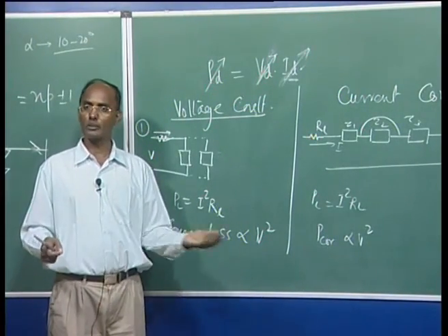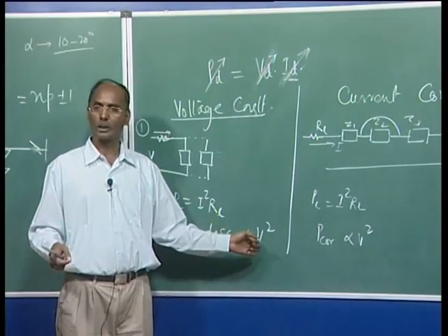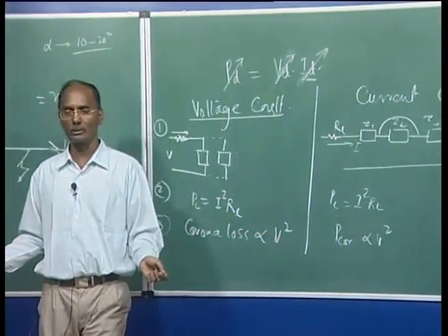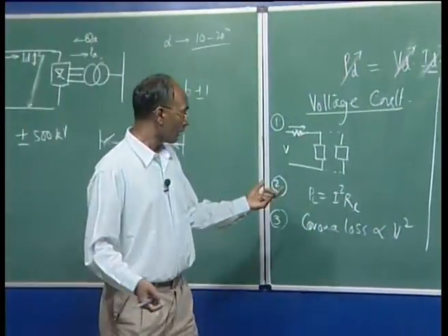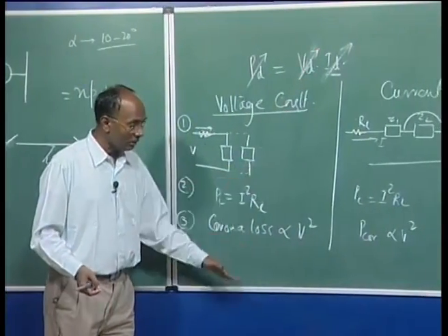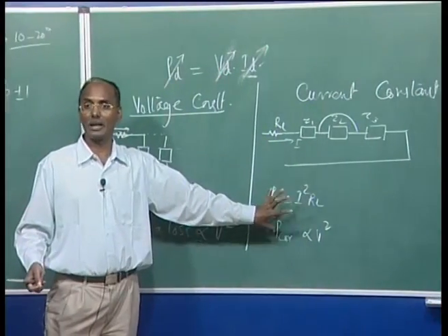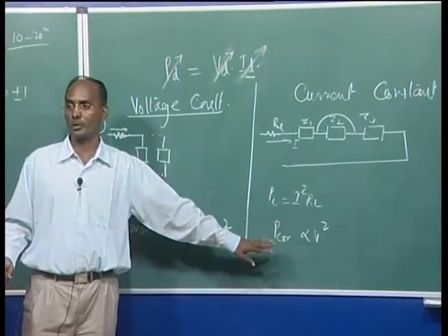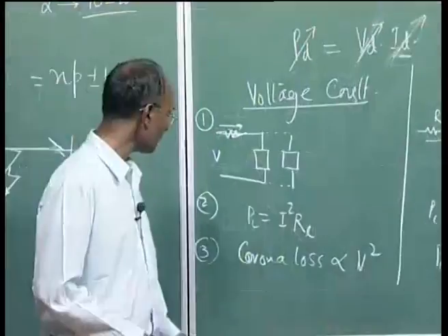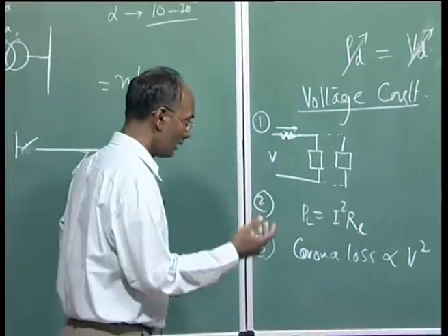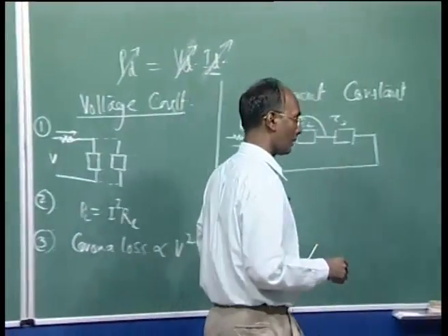So if it is less than, suppose you are operating at 400 volt, this is 0, corona loss is totally 0. So again, that's why here we are going for HVDC, high voltage. In high voltage these losses are significant, corona loss as well. Now the fourth is a very important one, and this fourth is nothing but related to your fault current.